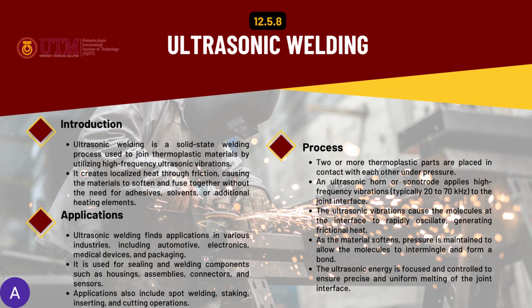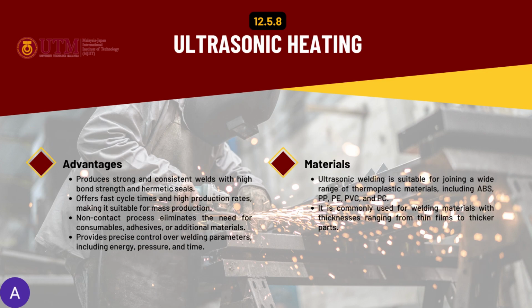So common applications for ultrasonic welding are in various industries including automotive, electronics, medical devices, and packaging. It is also used for sealing and welding components such as housings, assemblies, connectors, and sensors. Advantages of ultrasonic welding are that it produces strong and consistent welds, offers fast cycle times and high production rates, and provides precise control over welding parameters including energy, pressure, and time.